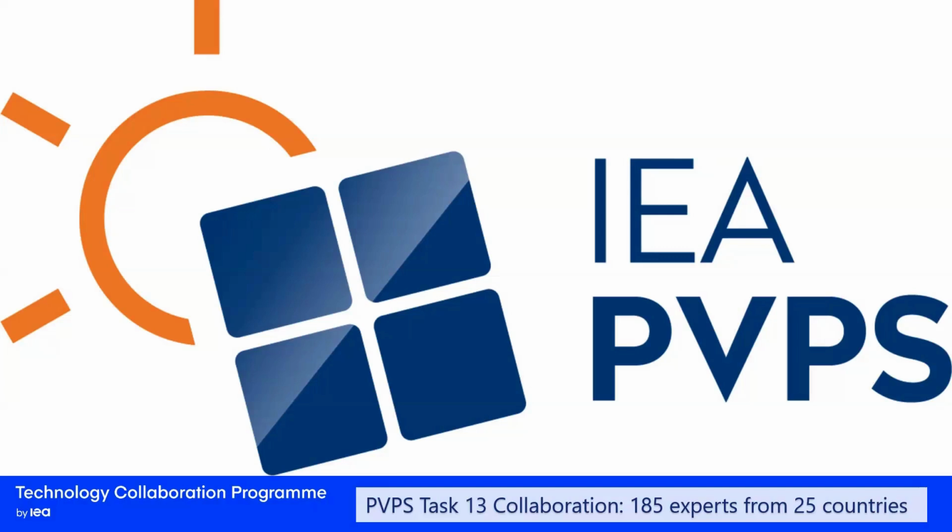Yeah, I very much agree. And I think one thing to highlight is that forecasting is key. We don't want sensors, and you need forecasting anyhow. But also, the gain of doing diffuse stowing is pretty small, but the penalty of diffuse stowing when you should be tracking is pretty high, right? So it's a skewed sort of return on investment distribution.